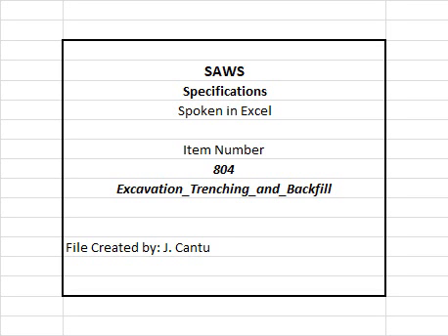E. Unless otherwise indicated, excavation shall be by open cut, hand, backhoe, hoe-ram, rock saw, or other approved method. F. Short sections of a trench may be tunneled, if the pipe or structure can be safely and properly installed or constructed, and backfill can be properly compacted in such tunnel sections. G. Tunneled section must be authorized by SAWS engineer prior to start of construction. H. Where over-excavation occurs and when not as directed by the engineer or inspector, the undercut trench shall be restored to grade at no cost to SAWS by replacement with a material conforming to the requirements of the bedding material or a material approved by the engineer.